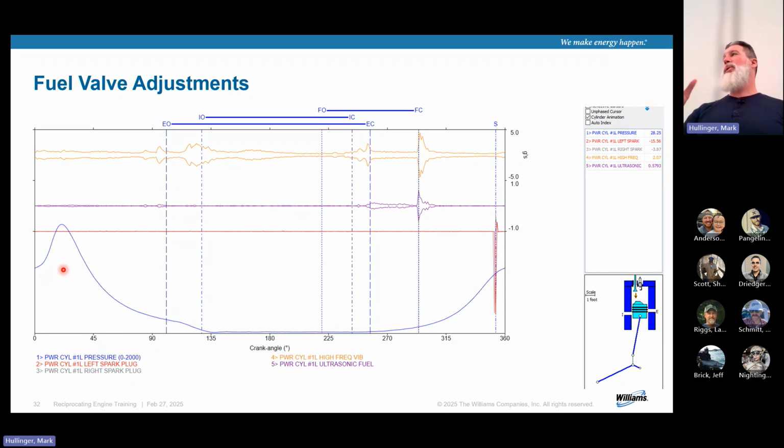And what I mean by that is when we're taking data. Our engines are timed automatically correctly, except for when they aren't, but our controls are timed correctly. If you have this timed off, the picture is going to look like a different picture, and you can't get any diagnoses off that. So the number one mistake we make, timing's off. The number one thing you need is timing has to be correct.